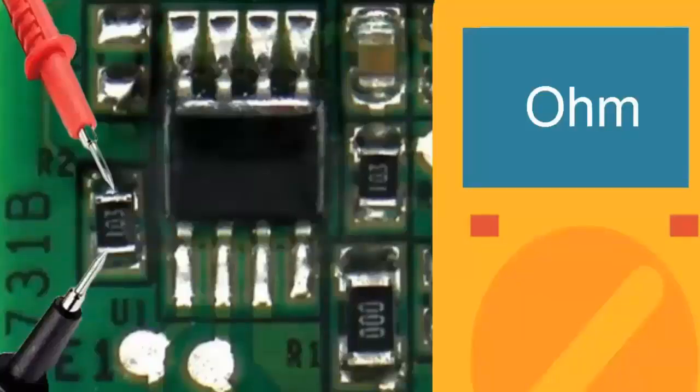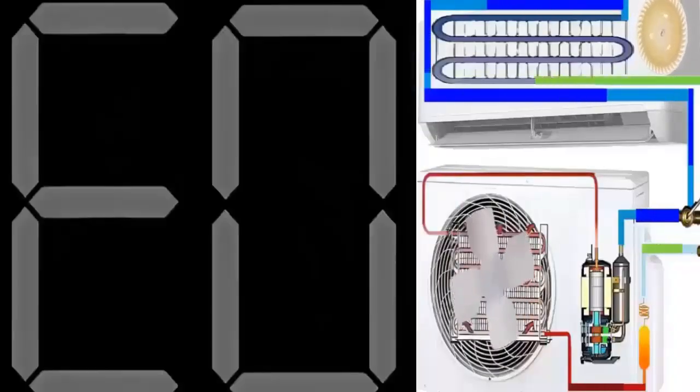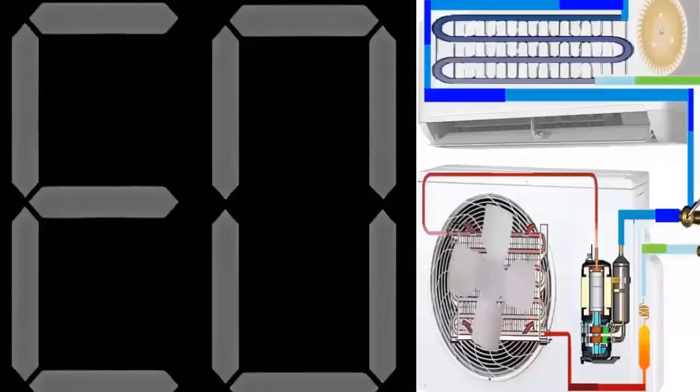D. Turn the unit back on and check if the error persists. If the issue continues, replace and reprogram the EEPROM or use one from a similar electronic board.